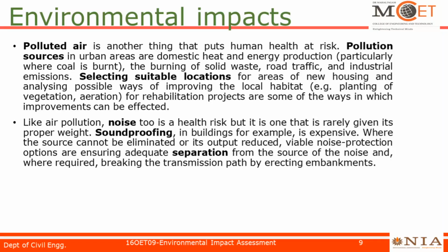Like air pollution, noise too is a health risk, but it is one that is rarely given proper weightage. Soundproofing in buildings, for example, is expensive. Where the source cannot be eliminated or its output reduced, viable noise protection options are ensuring adequate separation of the source of the noise, and wherever required, breaking the transmission path by erecting embankments. That is, you build some barriers to prevent the movement of noise from one place to another, or maybe movement of noise into the buildings.